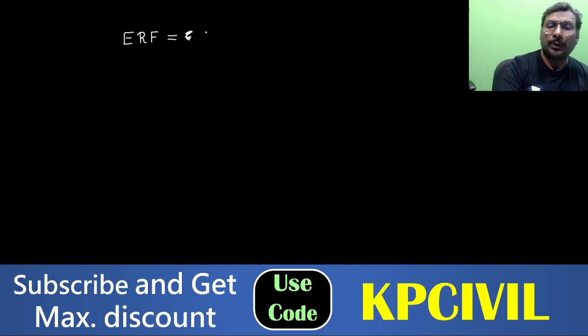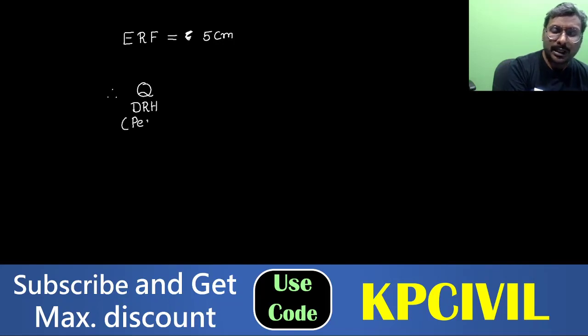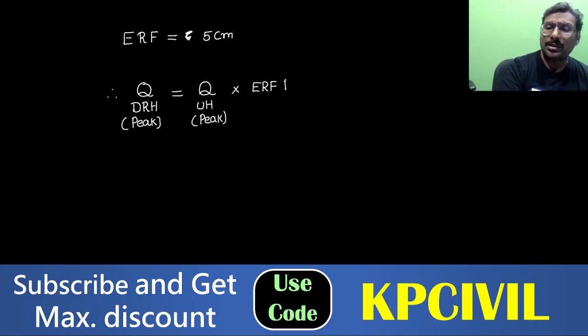So for the peak discharge of the direct runoff hydrograph, how can you calculate? The peak discharge of the direct runoff hydrograph is equal to the peak discharge of the unit hydrograph into the effective rainfall depth. This is the only formula.